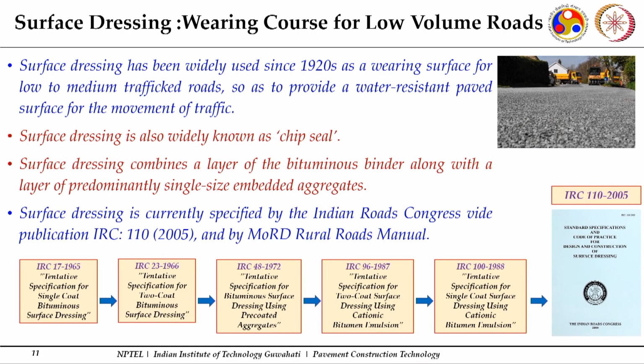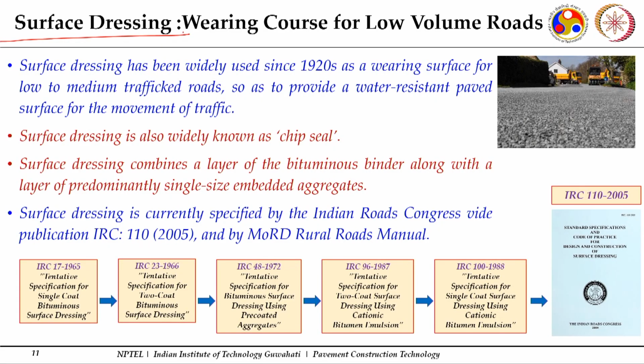Now, these are some of the courses which we prefer to use on different kinds of national highways, state highways and expressways. Then there are some typical mixes which are often used for low volume roads or for urban sections where you do not experience a significant amount of traffic in terms of axle loads. One of them is surface dressing. This surface dressing is used as a wearing course for low volume roads, and it has been popular throughout the globe since the 1920s.